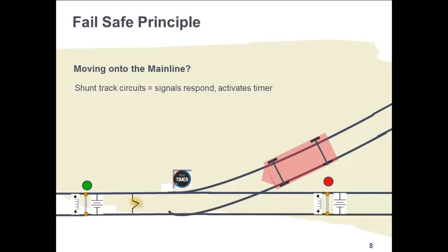And who sets the duration? And what is a typical duration? The signal design engineer sets it to fit the type of trains on the line, their speeds, lengths, braking distance, etc. After running time for typically 5 to 8 minutes, the electric lock on the switch is released. Then the trainman on the red train walks over to the switch and hand throws it. He or she walks back to the train and moves the train onto the main line.